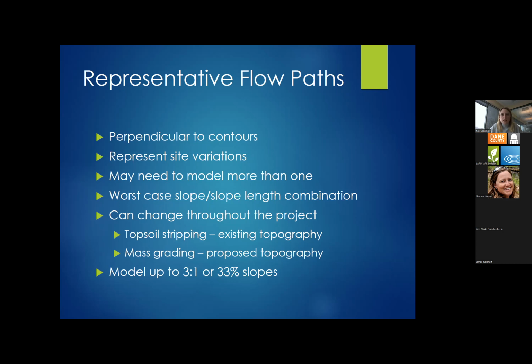The DNR guidance says not to worry about areas that are less than 10% of your site or less than an acre, but we would like people to still consider these areas. So just keep in mind that if you're submitting to Dane County, we would like you to look at all of the steep slopes too. And then when you fill these out and when you do this for yourself to try to find your representative slope, feel free to send us USLEs for multiple slopes. That way we know that you've done the work, you've looked into it. Otherwise, we likely are going to spend time checking ourselves.